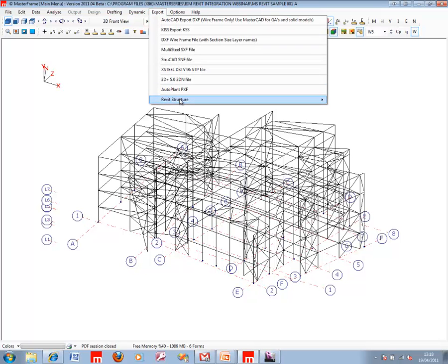One of the things that we do need to be aware of, and people do often forget, is when initiating something from MasterSeries towards the Revit Structure side of things, Revit does distinguish between say an inclined beam member and what would be a brace member. So for example, in this roof here I've got an inclined beam member, but also at a similar slope I've got some in-plane roof bracing members. It's important that Revit understands that one is a brace and one is a beam element. MasterSeries doesn't really worry about that. It's just a structural model, and its properties are what its properties are.